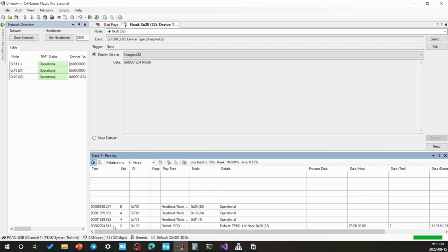Yeah, so it's right, because the only reason that you saw it 2 times was that in the process of programming it reset the microcontroller 2 times, so that's why you saw 2. But yeah, you see, once we receive it, and that's it. Now we want to trigger the TPDO to be sent by ourselves.